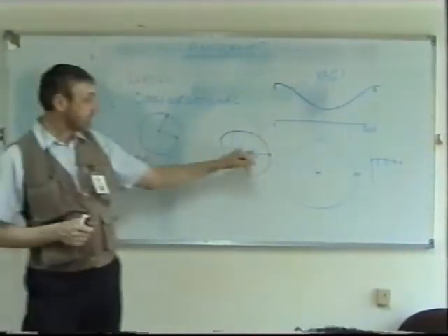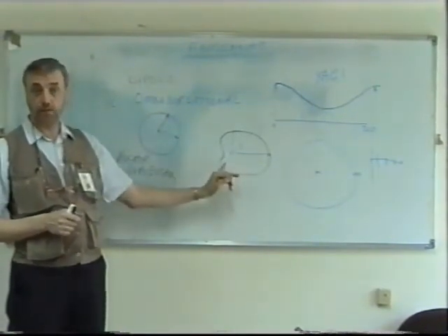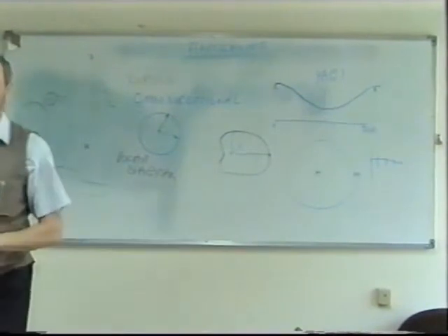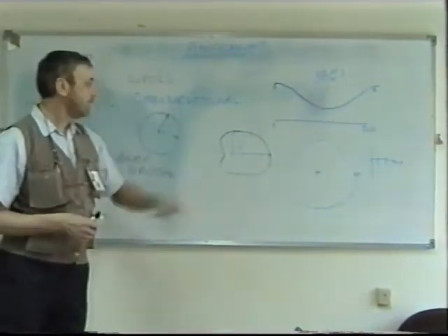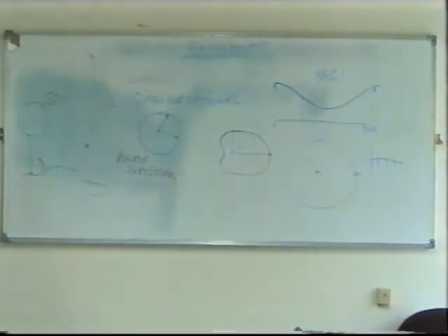Because although it is directional, there is still some radiation backwards and to the other sides as well. So it doesn't necessarily lose it altogether. The reason why we make it directional is to improve the signal gain, what we call the gain of the antenna, and to make the signal to noise ratio higher. But it doesn't necessarily mean he loses it altogether if you face it the other way. That's the advantage of a directional antenna, which is the third one. Yes, the higher antenna gain.